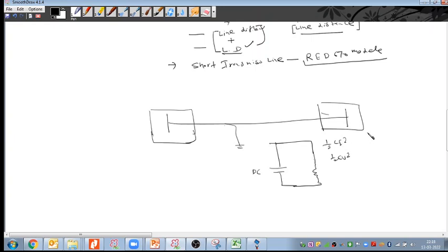First of all, they have the higher energy, and with time they are discharging the energy, and after some time it will come to zero. So this waveform will not be sinusoidal, it will have this exponential decaying nature, and that we are calling the DC component.